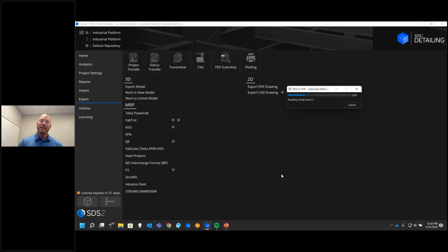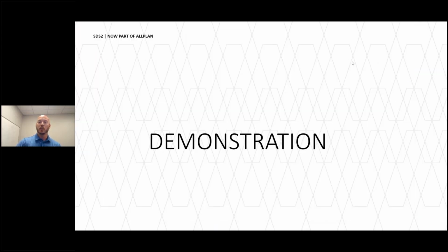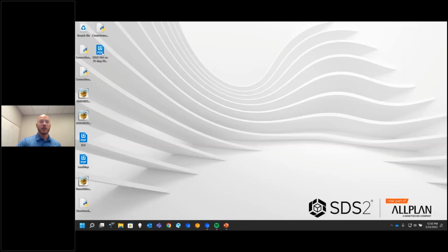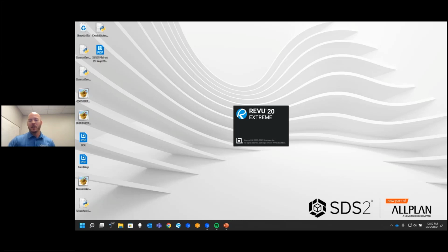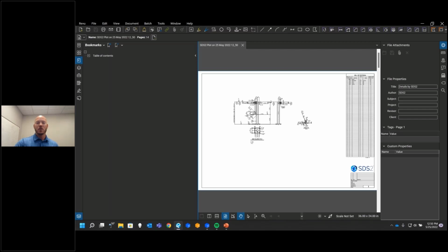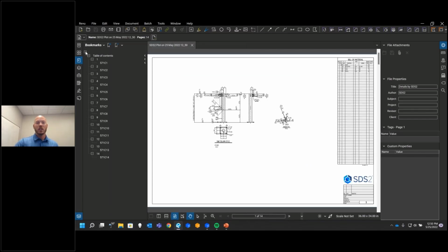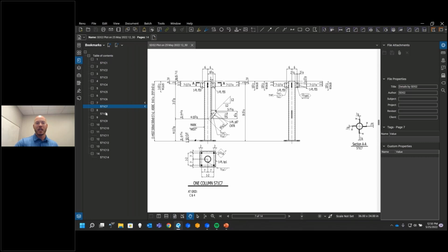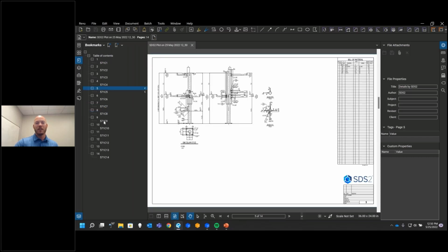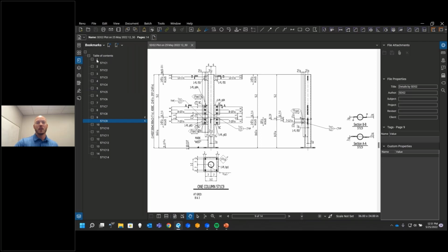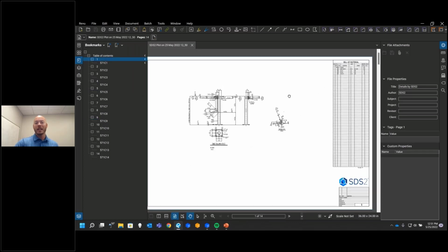So if I do a complete package where I have the erection sheets, detail sheets, submaterial sheets, or gather sheets all created, all the individual piece marks on those sheets will be hyperlinked. I don't have the full package, again, time constraints here. A couple things I do want to point out, however, we do a table of contents here, so nice, easy navigation. You have your sheet number, you can go to that full sheet or drill down to the individual detail on there.